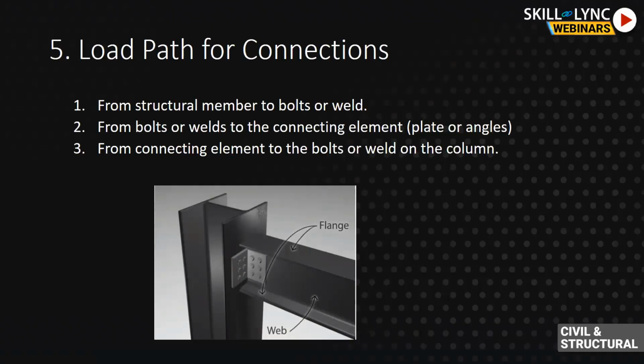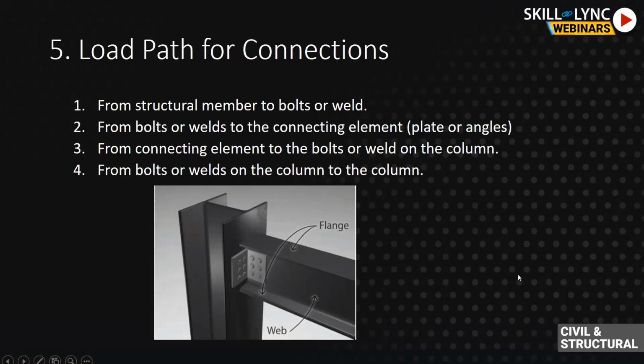and the column will be loaded by the bolts under the bearing. So the forces will then be transferred to the column, which will take it to the foundation. So the load path is as follows.